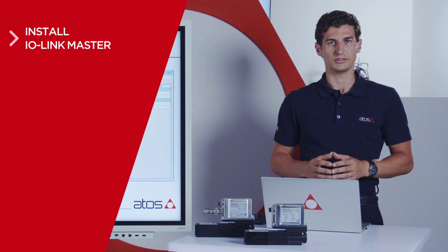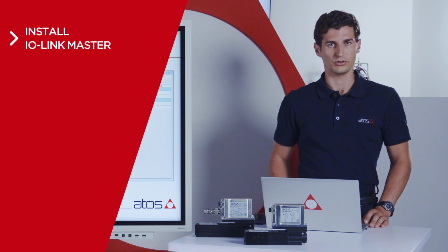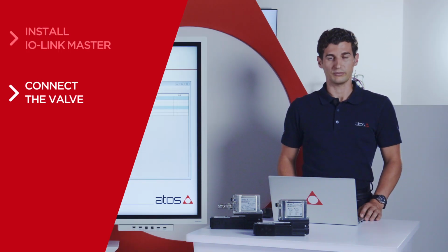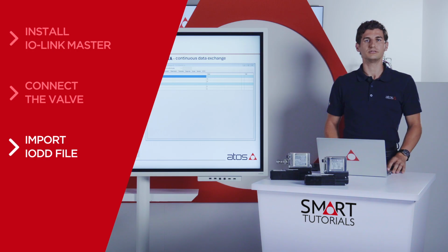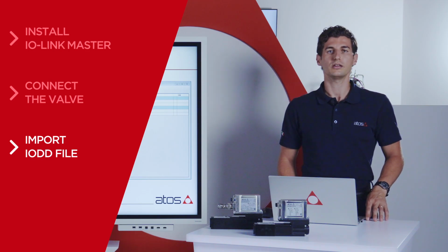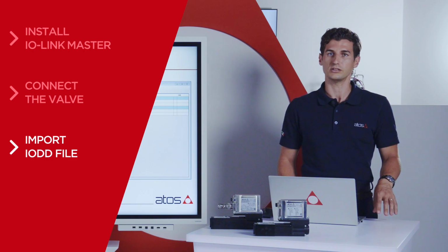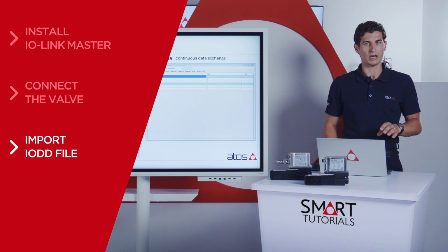Let's have a look at how to integrate an IO-Link valve into your system. Install the IO-Link master. Connect it to the PLC using a supported fieldbus protocol. Connect the valve to the IO-Link master. Check the technical tables or the quick start to correctly wire it. Okay, now import the IODD file into your PLC. The IODD file lets your PLC recognize the valve and access its parameters. The IODD file is available in the download area of My Atos section, where you already downloaded the manual of IO-Link.